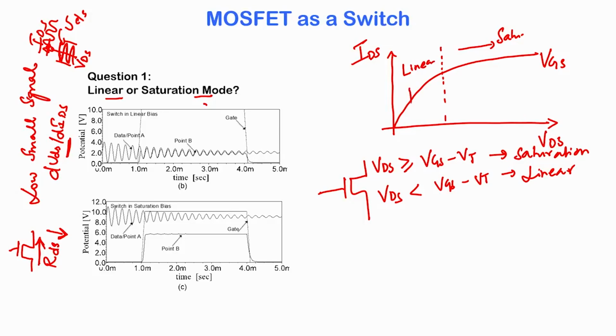We have set a VDS and now we are going to fluctuate a small signal VDS around this, and we are going to see a fluctuation in the current in response to that. So, this slope is essentially the resistance. As we move the voltage up and down, the current moves up and down. So, the current changes by that level, and therefore, the resistance here is some value which we will call R linear, which is your dVDS by dIDS.